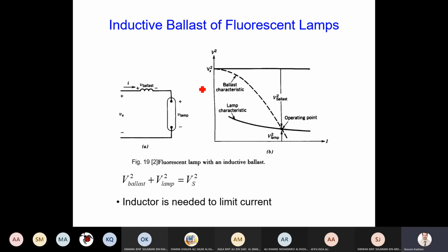Another example, lighting. We know lighting is available in our homes. Wherever we go, lighting is an important issue. Now, how does lighting work? In the conventional one, we have a ballast, which is a choke inductance, at the end. And we have a lamp here. Inside the lamp, there is gas. The choke will reduce the absorbed current, but the voltage will be high, which makes a spark. When the spark goes through the gas, sorry, it gets lighting. We see light coming, okay?